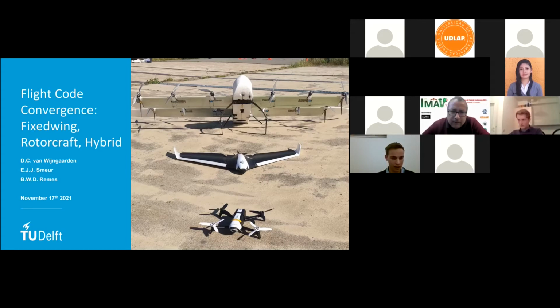Yeah, basically you can hack those Parrot drones. We are using Paparazzi UAV. I think there's just a Linux computer running on it, so you can access the drone using a telnet connection, and you can basically flash your Paparazzi software on those Parrot drones. Currently in Paparazzi UAV, you can flash the Parrot Disco and the Bebop 2. In our paper, we also made a reference to the branch we use, so if you want to test this code yourself, it is ready to fly.